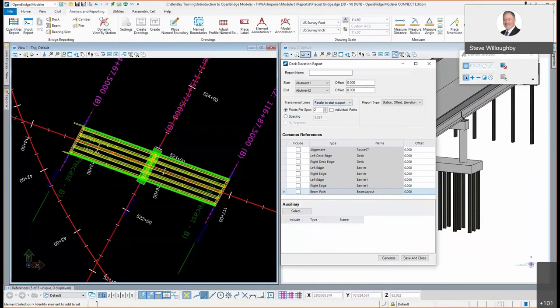How does it handle straight girders on a curved alignment? Really well. I mean, you can absolutely lay out straight beams on a curved bridge. Or you can have, let's say, a straight bridge on a curved alignment as well. And you play with the bearing offsets, right? The distance between beams, that's how you play with it in the beam layout.